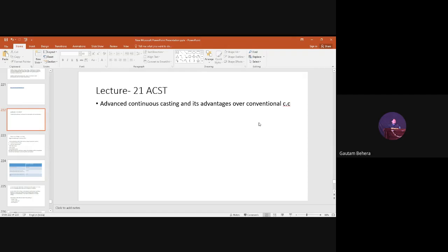If you have a car and you look carefully at the outer body, if it is made of steel, the thickness is like 1.3 mm or 2 mm. It varies from company to company. This is the range, 0.77 mm to 3.3 mm, of the sheet, or you can say strip.